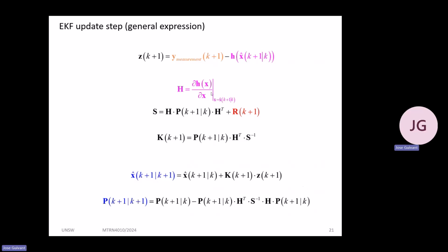The important thing, we had to provide the measurement that we just got from the sensor. We need to exploit the prior expected value. We need to exploit the output equation that we know, our nominal output equation. We need to calculate, or we did calculate this before, the analytical expression, the Jacobian matrix of the output equation with respect to the state vector. We do this just once. We get the analytical expression and we just do the evaluation on the current expected value of the state vector.